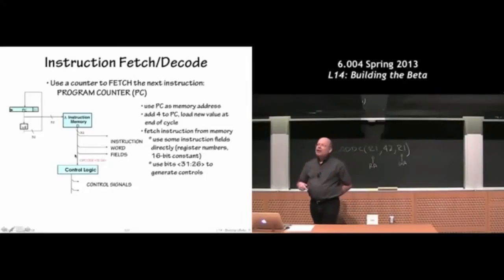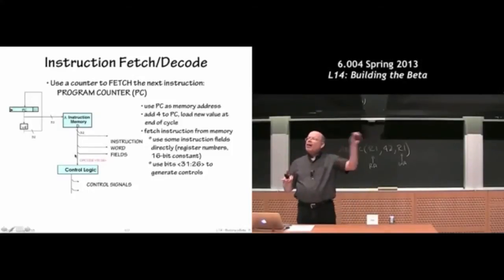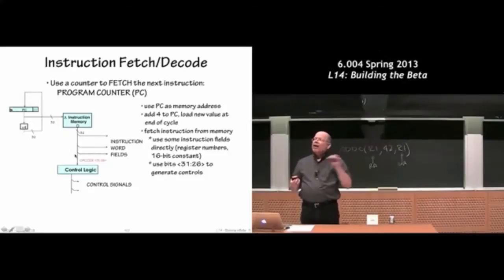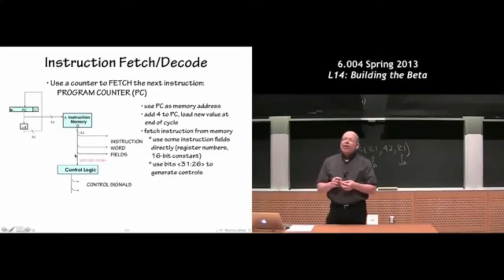Why is a PC a multiple of 4? Just to reprise our apologia about byte addressing. We use byte addressing, in other words, we think of each 8-bit quantity in memory as separately addressable, so each one has a unique address. Because we are building a memory system that only fetches 32-bit words, and the load and store instructions always fetch a 32-bit quantity, we will always be sending over an address that points to the low order of the 4 bytes we want to fetch from memory.